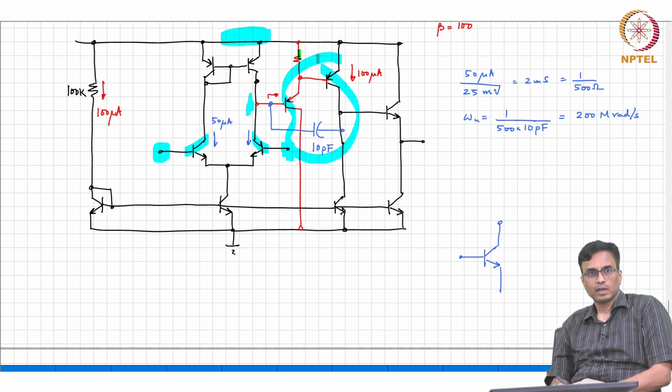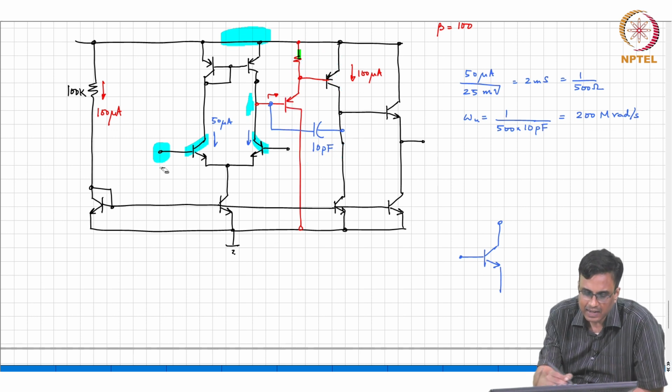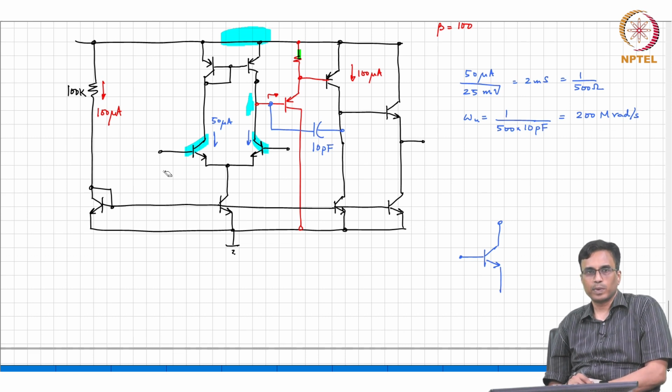So, what will happen? If you flip the signs of the op amp in a negative feedback loop, the output will go to either plus VDD or to ground; it will saturate, right. It will get stuck in that state and stay there, and the only way to fix the circuit would be to turn off the supply and turn it back on again, right. And that of course is not a good thing, because just imagine you are on a satellite going to Mars and suddenly something like this happens. There is nobody to go and switch off the circuit in outer space and then switch it back on again, correct.